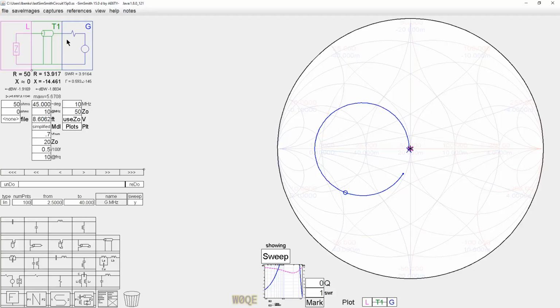And we're going to put this into our antenna analyzer. We're going to use enough of a length of coax here to give us a full revolution on our plot. I don't know what kind of analyzer you might have, but let's suppose your analyzer can go up to 100 megahertz. Then we would need something at least 4 feet long. Let's say 4 feet. It doesn't matter if it overlaps.